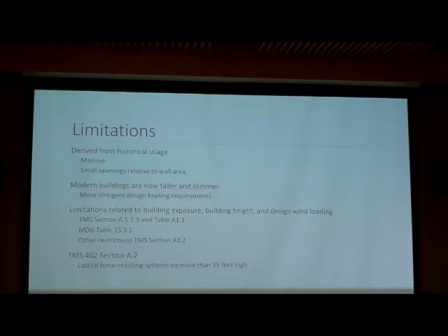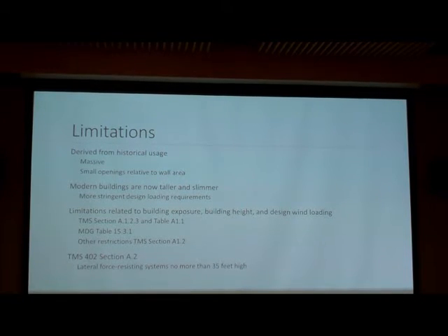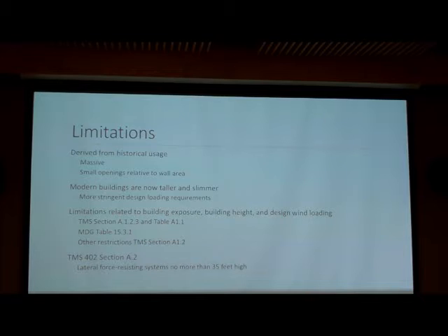An issue with that today is that our buildings are now taller and slimmer, and there's more stringent design loading requirements that we use today. Also, most buildings we want the big picture window. We want wall or floor-to-floor glass, and that's not possible using empirical design.